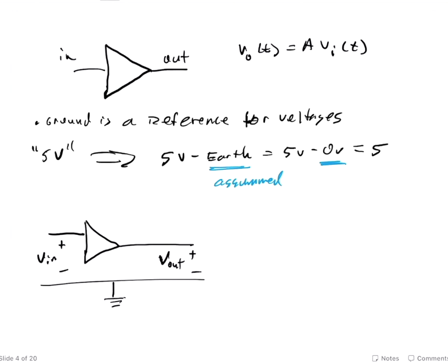In the lab, when you can, you should make this earth, make this ground. And the ground connection in your house or in the lab, that third prong on your electrical circuits, is actually connected to usually a bar of some kind pounded into earth. It's supposed to be pounded into wet earth.